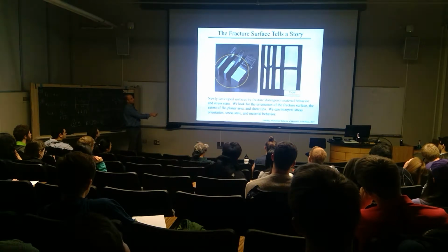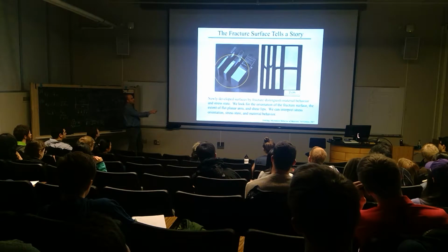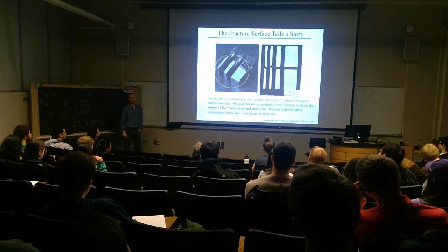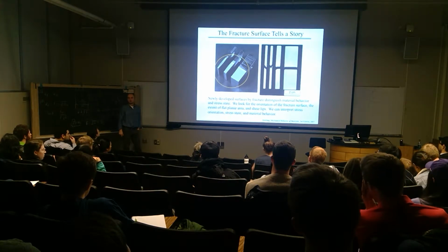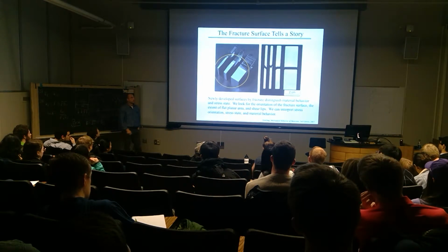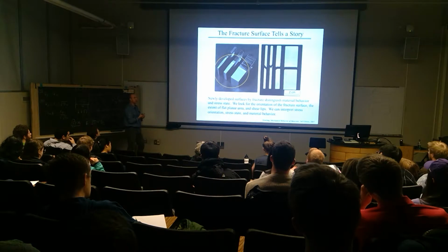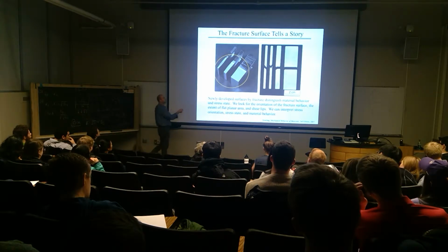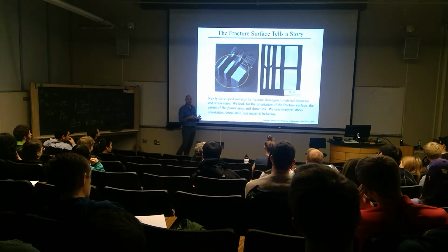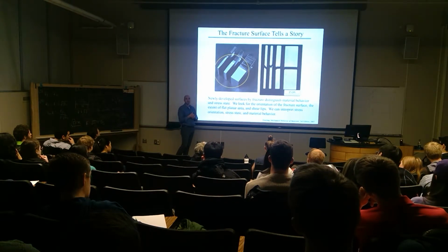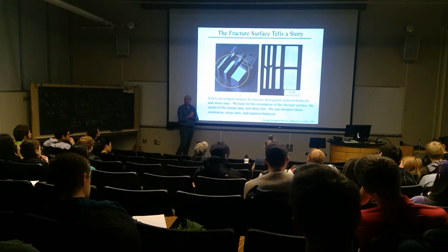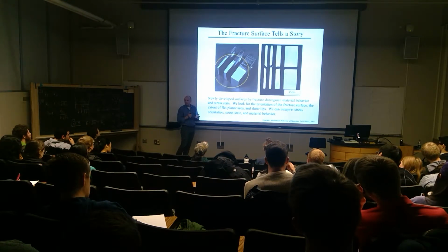This is the Z direction, and you can see that this went from a slant fracture to a small amount of shear lip to almost no shear lip at all. What does that tell you? Slant fractures or shear lips indicate ductility, and so lower amounts of shear lips means less ductility, and no shear lips means almost no ductility. And this is the same material. This is just a change in the stress state, right?